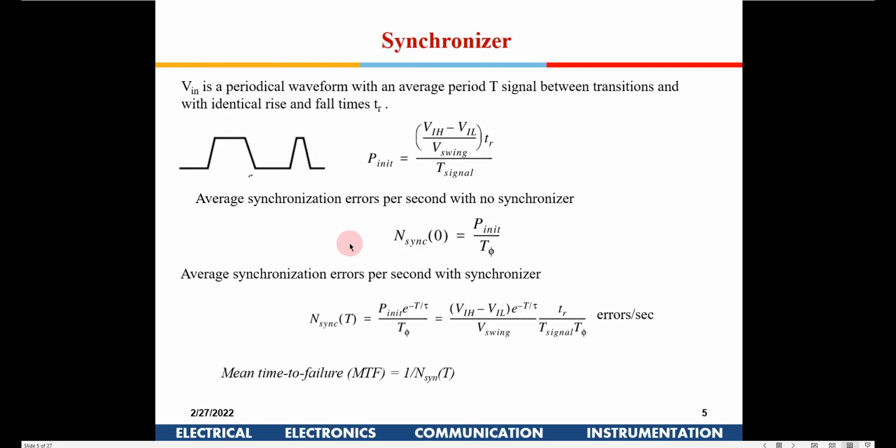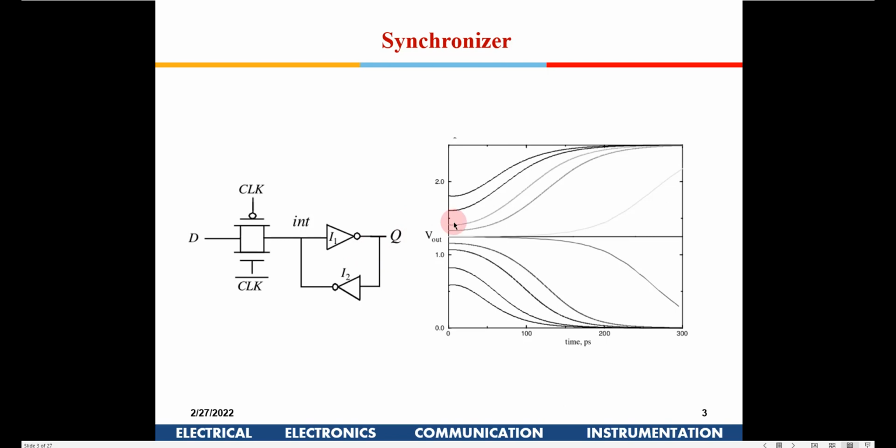Does this have an impact on the maximum clock frequency, right? Sampling, see, these settle within a few picoseconds. With the present technology, where clocks are in gigahertz, and gigahertz corresponds to nanoseconds, this gets settled within a few picoseconds, so that is not a major issue. We are just waiting for a few picoseconds, that's all.